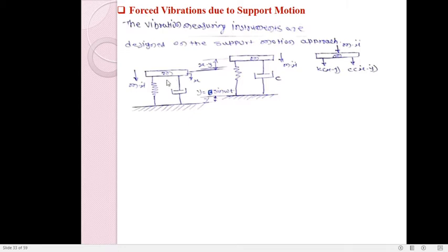So this chassis, because of the engine input, gets displaced in the downward direction by amount x, suppose, and this base, these are wheels, because of the road surface get the excitation and get displaced by amount y. So the total deflection might be x minus y or sometimes x plus y, that depends upon the nature. But this y we will assume as an exciting force, or we can say periodic force supplied to the wheels, and have the value y equals b sine omega t.